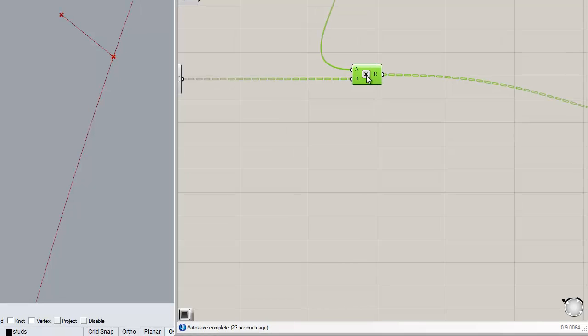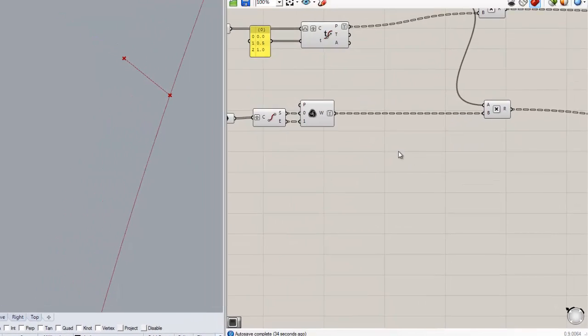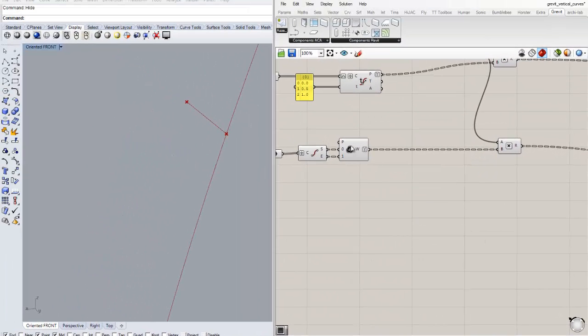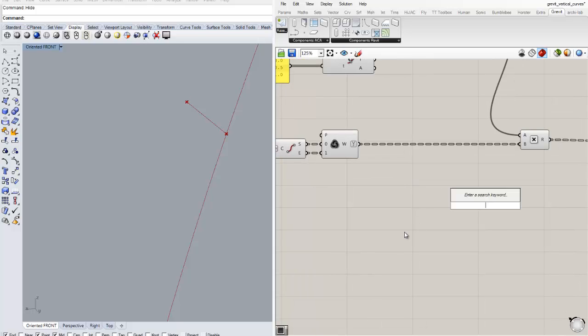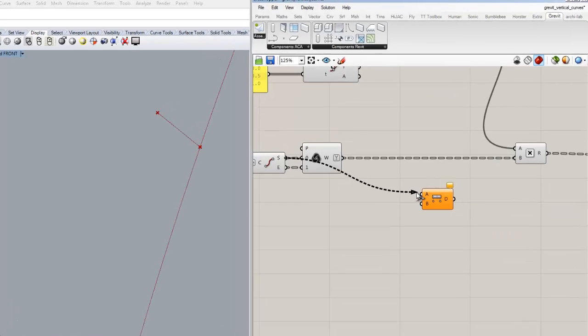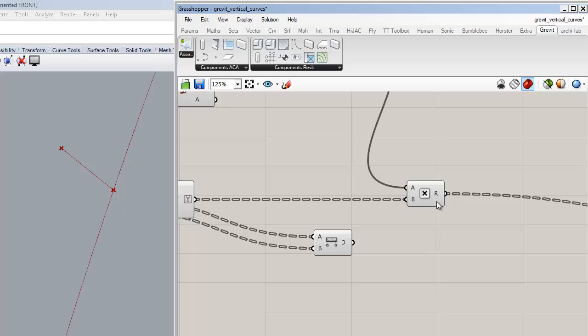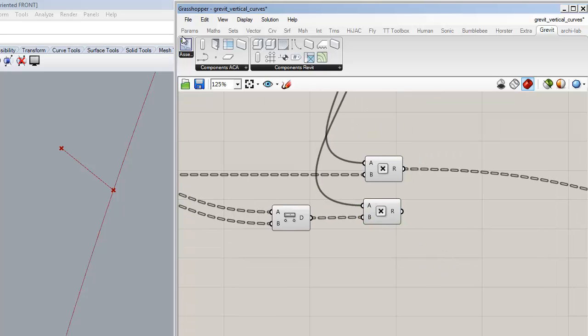So let's say that you want to schedule the length of that line in the schedule. What I would do is measure the distance between those. So let's collect those points and measure the distance between the start and end point. You can type in distance between start and end, and then again we have to convert it to feet. So that will be our distance.